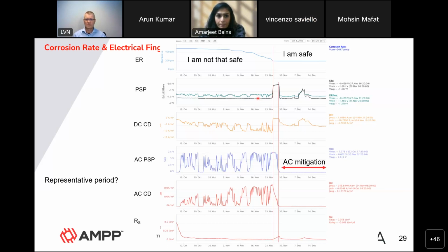Yeah, good question. The lifetime of an ER probe is in principle infinite, considering the case that you do not have any corrosion. So if you do not corrode on your ER probe, it will keep on working as long as it's not cut down or stolen or vandalized in any way. And therefore it can be very long time reliable.